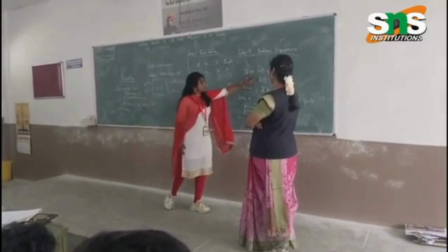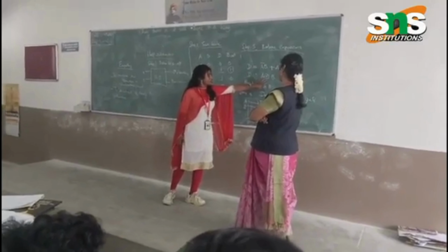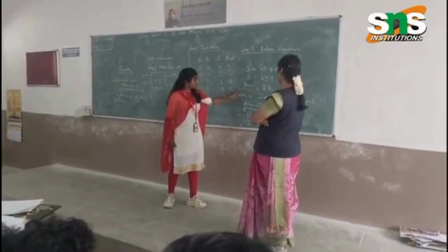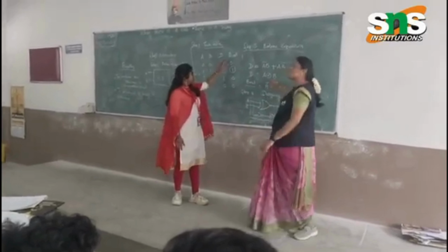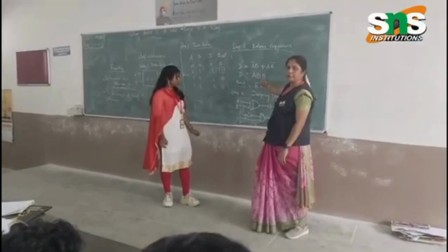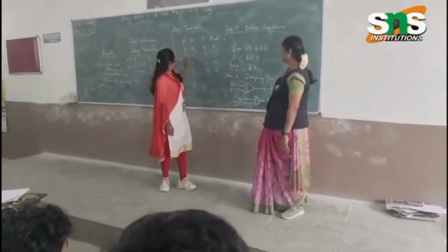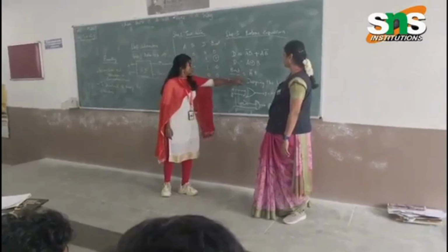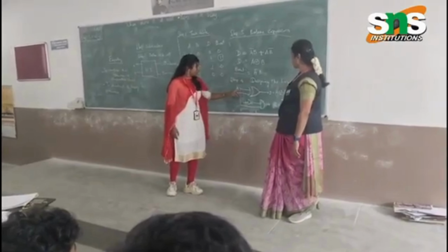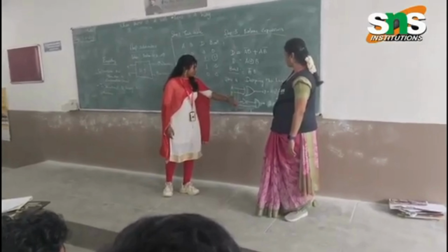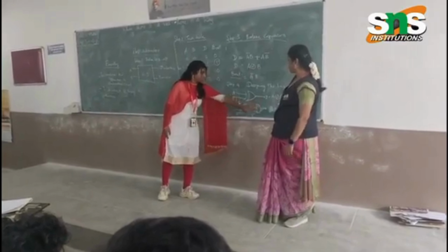This is the expression of the XOR gate, so it is A XOR B. In borrow out, the output is 1 for input 0 1, which is A bar B. In step 4 we design the logic gate. We draw A and B, then give a NOT gate to get A bar. Then we get the answer.